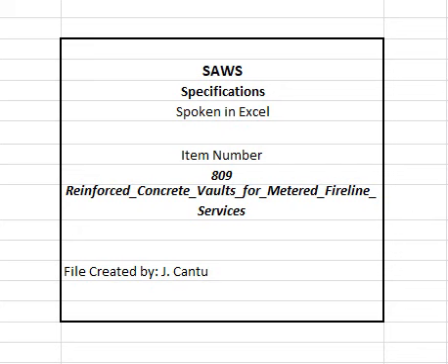1. Testing shall be performed by qualified individuals employed by approved independent testing agency, and conform to requirements of ASTM-C 1077. 2. Take concrete samples in accordance with ASTM-C 172. 3. Make 1 set of 4 compression test specimens for each mix design at least once per day and for each 150 cubic yards or fraction thereof.